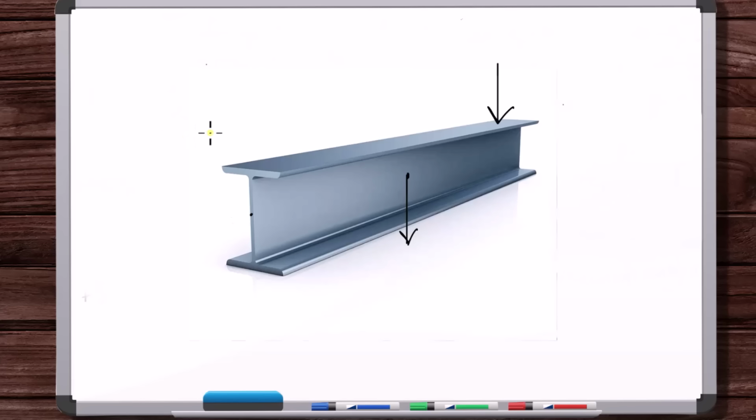And for the vast majority of problems, if not all problems in this course, it's going to be like we made a cut with a plane that's perpendicular to the axis of the member. The member is going to have some sort of symmetrical axis to it most of the time. Again, when you get to mechanics of materials, you'll get into more detailed analysis of this. And sometimes there might be potential that the resultant force is not at the centroid of the cross-sectional area. A lot of times it is, though. Most of the time it is for most engineering problems.